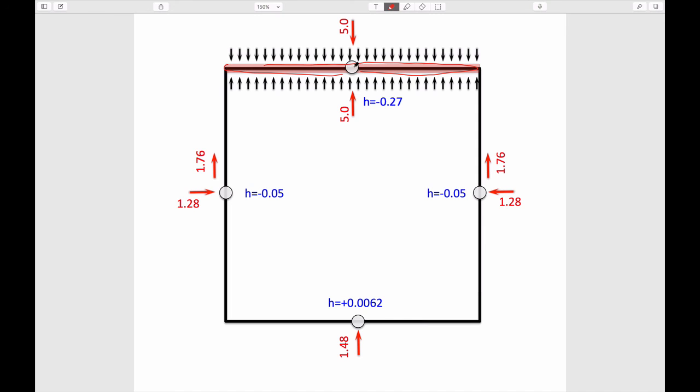And you can rationalize it. So you're sucking things into this slit. So you imagine that the velocities would be in the directions of these two arrows, right, into this. We're only calculating it at this particular point. We could calculate it at other points if we wanted to, but we're going to choose to do it in the middle of the elements. And so they're kind of unusual elements for us, right? Our finite elements have always been an element with a little node at each end. What we're doing is making an element with a node that's really in the middle where we calculate things. And so if you imagine stuff flowing into this, you'd imagine the big velocity here, into from both sides. So if you drew the streamlines for this, it would look like this, I think, right? You could imagine it looking like this.